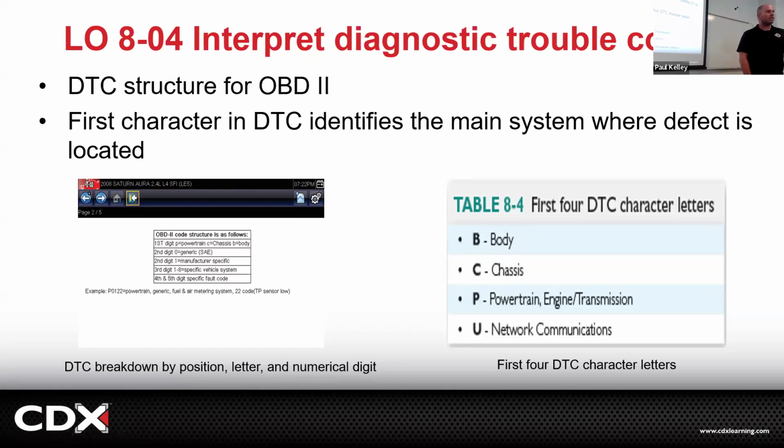They didn't. You know what they did? They made powertrain to make sure your emissions levels are correct. And in the meantime, you don't have any brake lights, and your brake pedal position sensor and brake pedal switches, you threw them out, they're not monitored, and we don't care. Make sense? All right, so just saying.